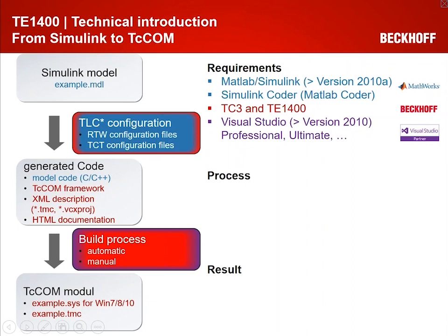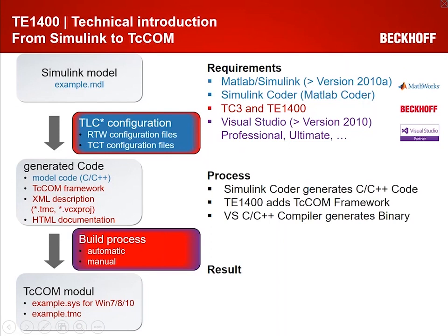And then the process is that we can get this C code provided by the Simulink Coder. We add our TcCOM framework around this C code, and we build binaries using the Visual Studio C compiler.